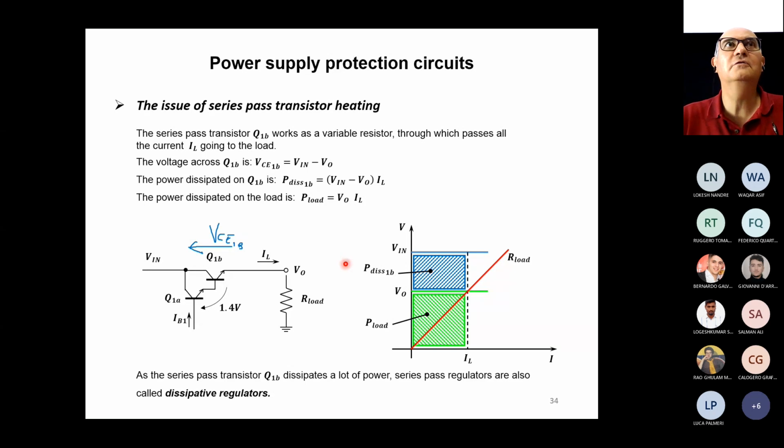But they generate a lot of noise, while these power supplies that we are studying here virtually generate no noise. So in very good equipment, for instance, in very good radio receivers, you don't want to use a switching power supply. You want to use a linear power supply. You don't care if the system has poor performance in terms of efficiency, but if you want to be able, with a radio, to pick up very low signals from distant transmitters, you need a system which has no noise.